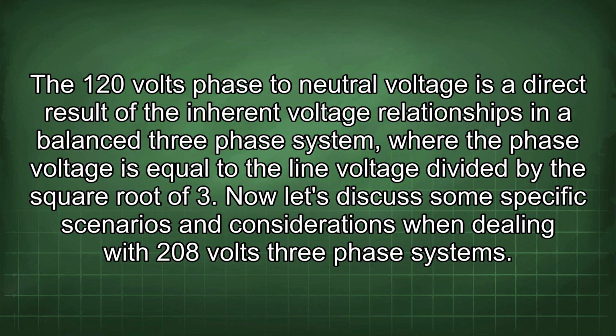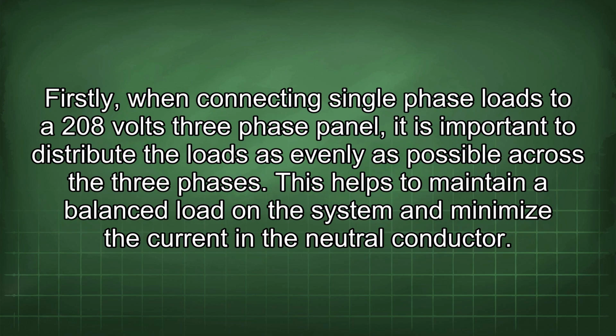Now let's discuss some specific scenarios and considerations when dealing with 208 volts three-phase systems. Firstly, when connecting single-phase loads to a 208 volts three-phase panel, it is important to distribute the loads as evenly as possible across the three phases. This helps to maintain a balanced load in the system and minimize the current in the neutral conductor.